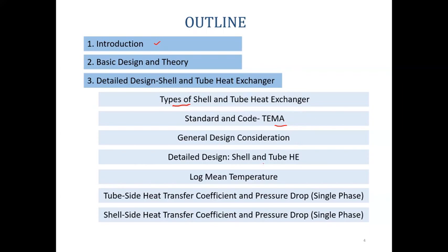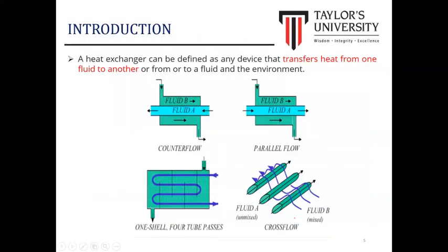Okay, general design consideration, detailed design on the shell and tube, log mean temperature, which is the basic concept for any design of the heat exchanger, tube side heat transfer coefficient and its pressure drop, and also on the shell side for both heat transfer coefficient and also the pressure drop. Okay, as introduction, a heat exchanger can be defined as any device that transfers heat from one fluid to another.